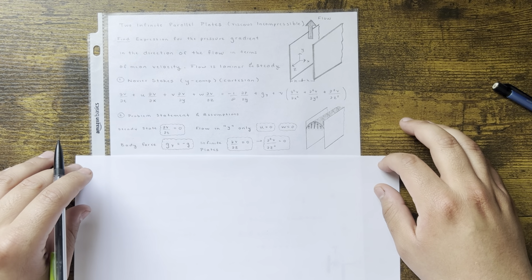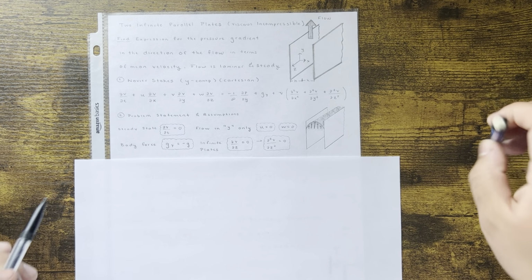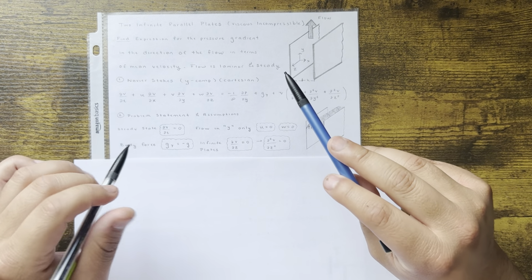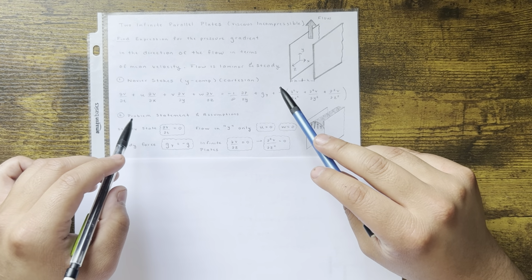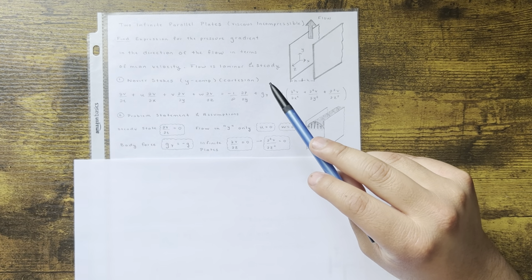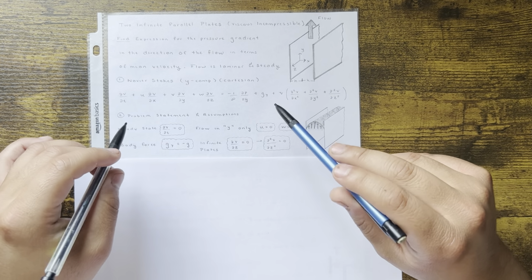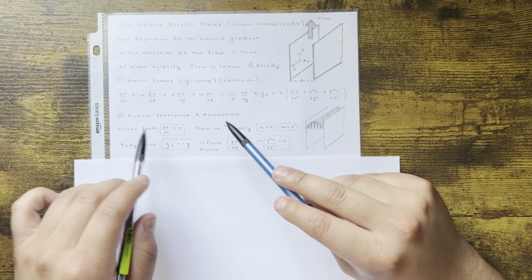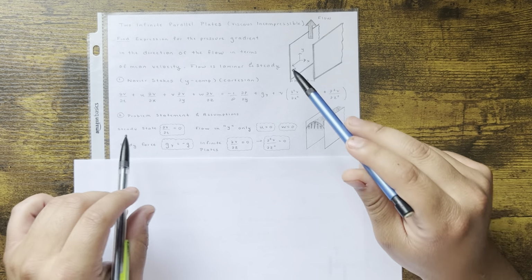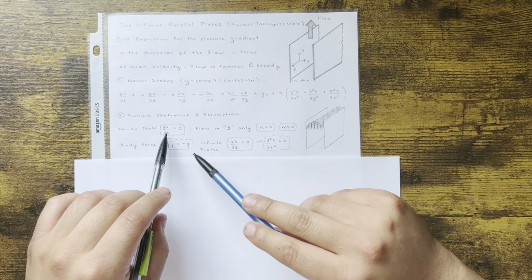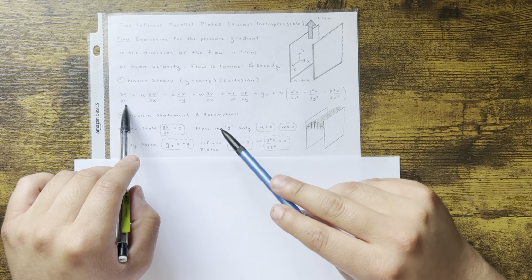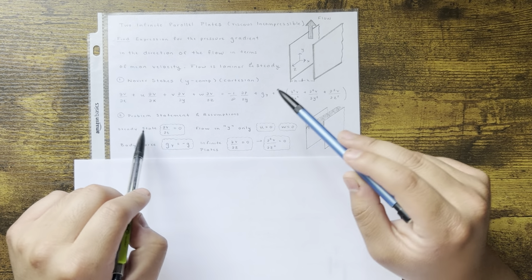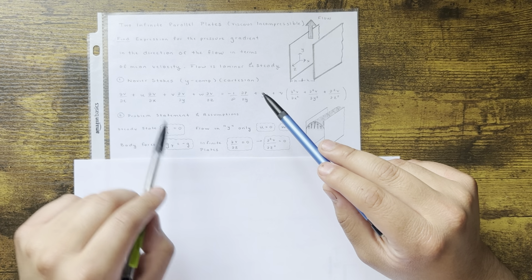So we go ahead and do that. Let's start doing the assumptions from the problem. You're dealing with steady state. Anything in the undergrad course is going to be steady state, just FYI. Very rarely do they give you guys unsteady state. Maybe crazier schools like UCLA do, who knows? But I know my Cal State just gave me pure steady state problems for the undergrad, so I'm assuming that's why you guys are here too. So steady state: the t term, anything with a t, is 0 because it doesn't change with respect to time. It's steady. So that term went away.